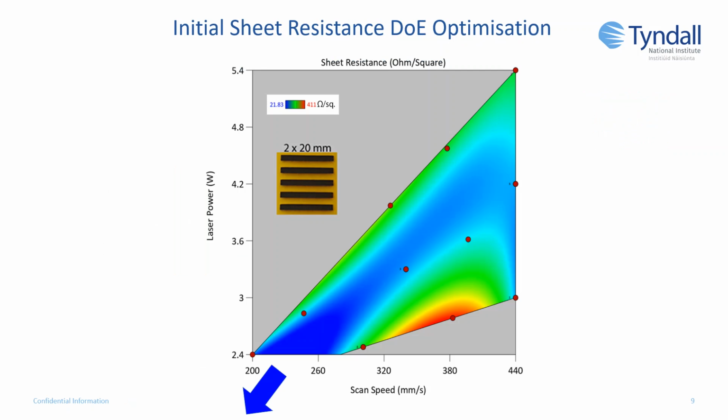Long channel, high aspect ratio, rectangular regions of laser-induced graphene were produced and contacted using a multimeter to estimate the sheet resistance. We did this to reduce our sampling times, as the time taken to land and re-land probes for traditional transmission line measurements would have been burdensome. The use of long channels was to ensure that the contact resistance was only a minor contribution to the estimation of sheet resistance. This approximation of sheet resistance had previously been verified using a test run of laser-induced graphene using current voltage sweeps under traditional transmission line measurement approaches.